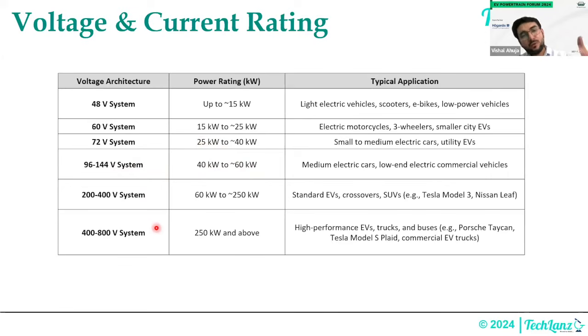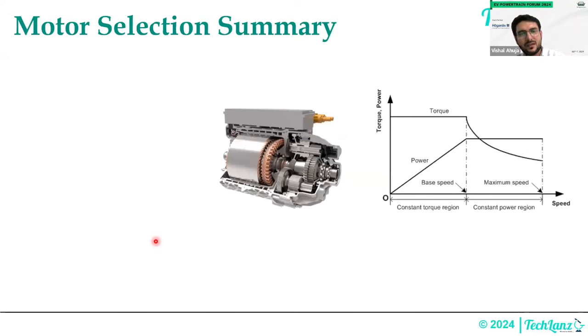When you talk about more and more efficient vehicles like Tesla, Ioniq, trucks, buses, what we have in India also, they use an 800 volt system because the current rating goes pretty high. The bus bars will melt otherwise, right? You need to go with a higher voltage system, right?